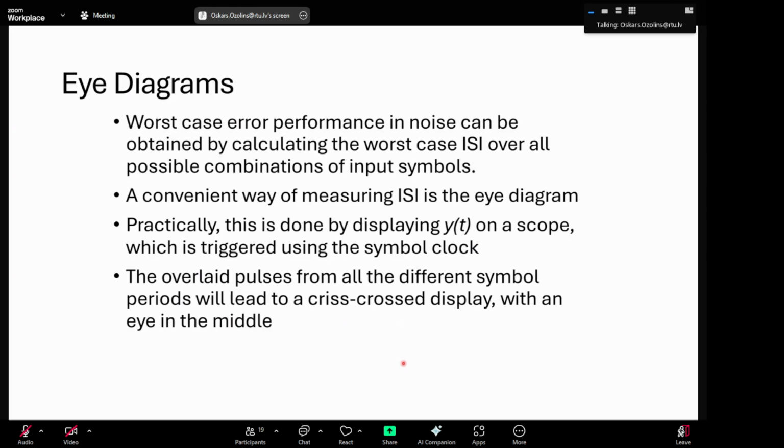You can look at intersymbol interference, and the noise impact here. You need an oscilloscope which has a clock signal to it, so you can visualize it, or you need to do this signal recovery in a digital signal processing model, when you work with a digital signal.